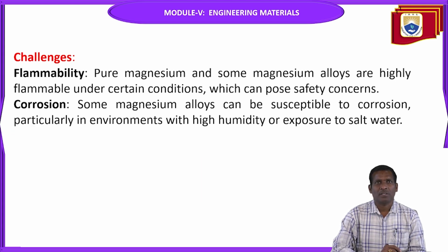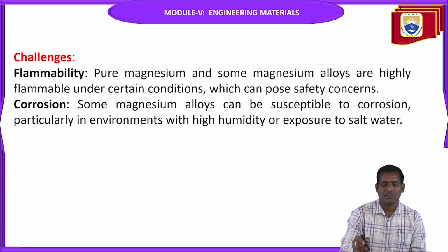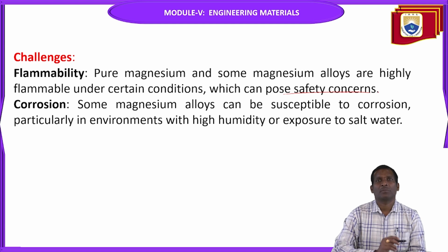The challenges are also there. One is flammability, another is corrosion. Pure magnesium and some magnesium alloys are highly flammable under certain conditions, which can pose safety concerns. So that's why safe material storage is required while storing these materials.